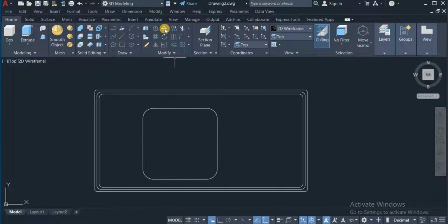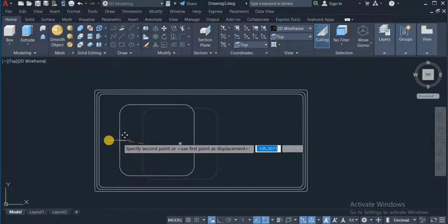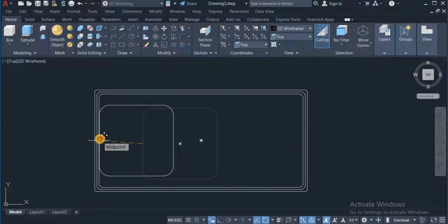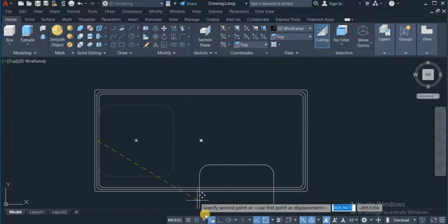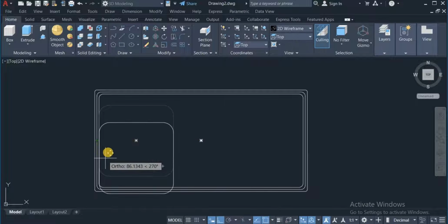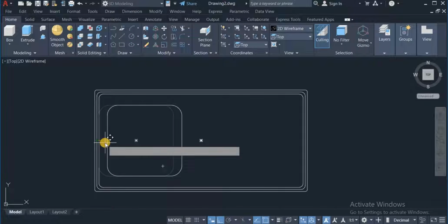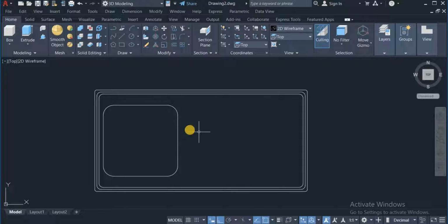Okay. Now I'm going to move this square from this midpoint and drop it on this very midpoint. Okay. So I'm now going to shift this square to the right by 20. So I click on the move command, click on this, pick from here, and move to the right by 20. I have to check the auto mode, so make this horizontal, okay. 20, okay. Now I'm going to draw a line of 100 from this very midpoint. Draw a line of 100 units.